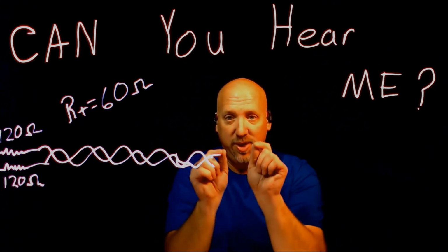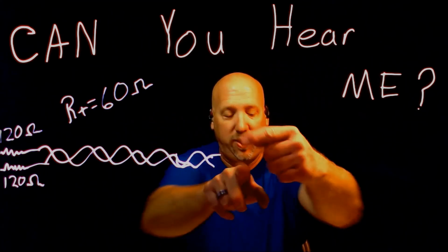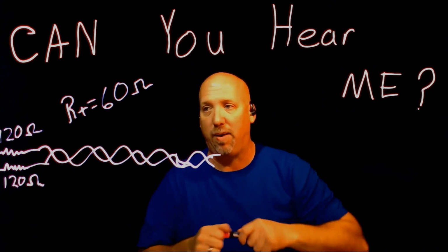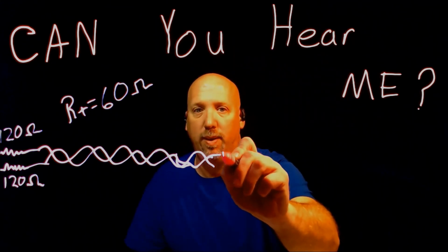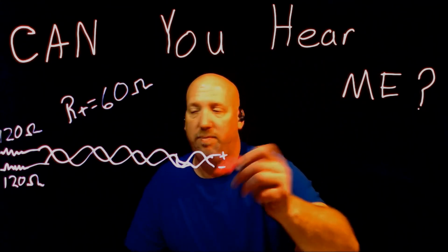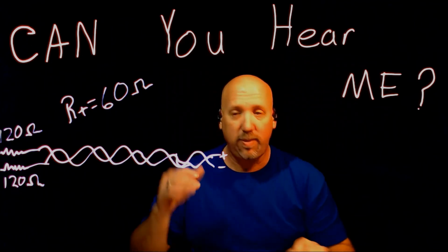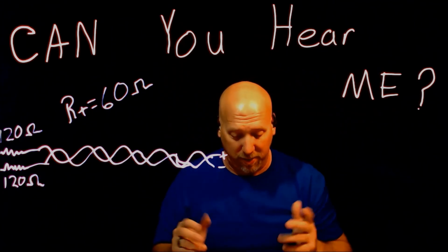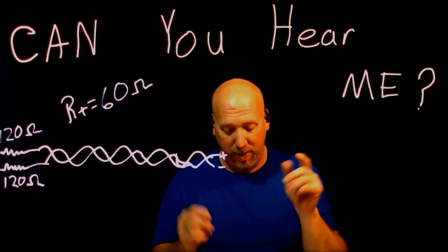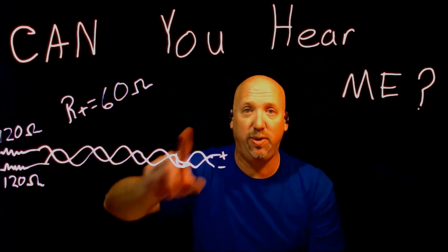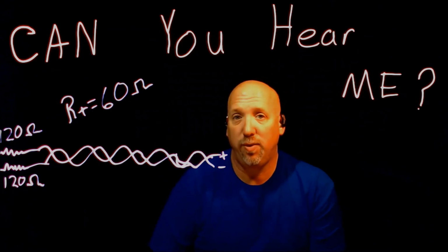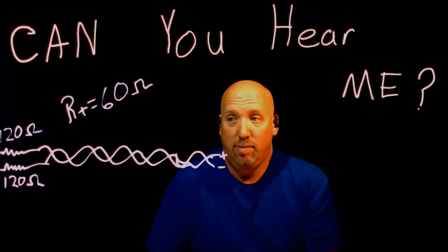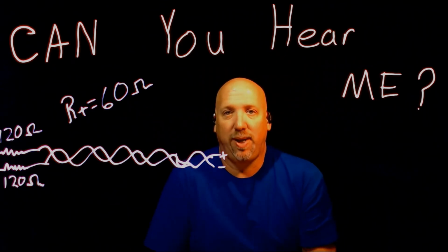So when you're checking for resistance in those two wires, positive and negative, because you have a power and ground, roughly, and you're checking the terminating resistors with no power on the vehicle, it's going to be 60 ohms. If you have more than 60 ohms, you have a problem with one of your resistors. That's a simple check. Sometimes it's the first thing you do.